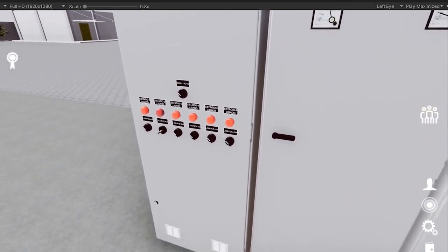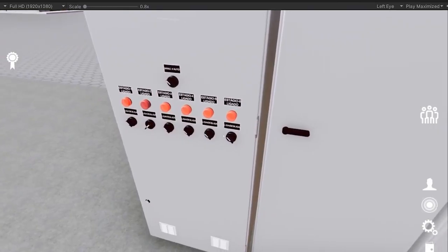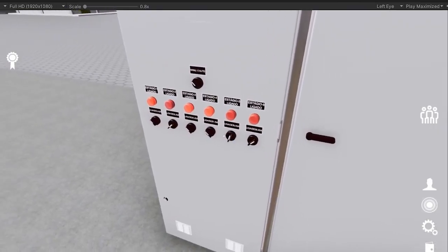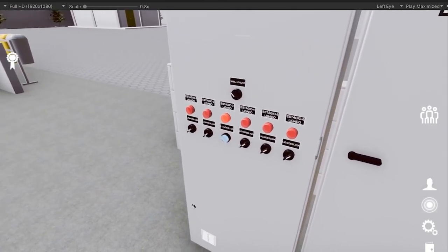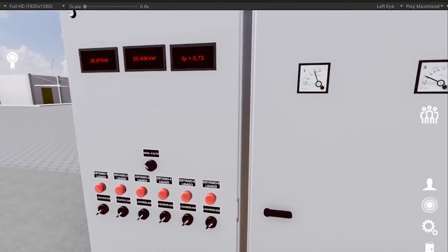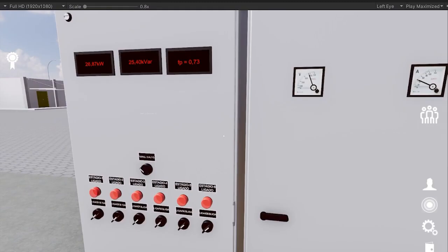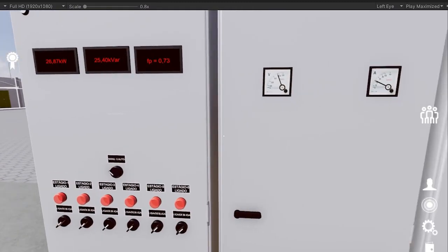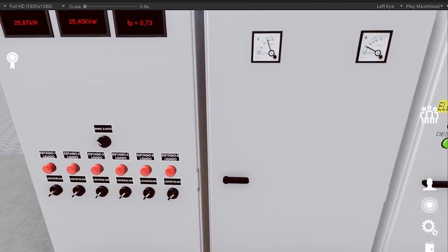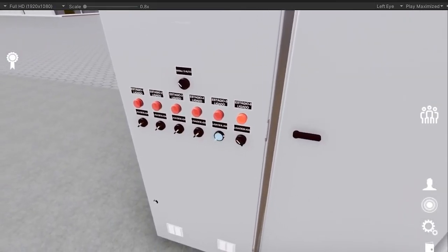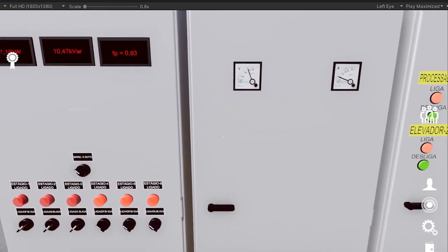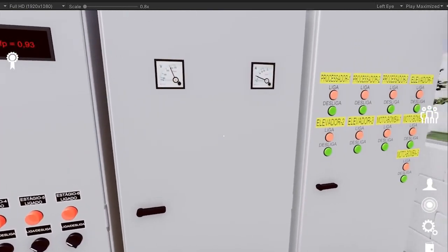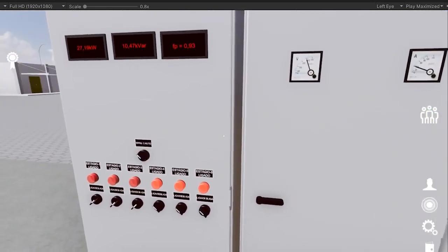This here, folks, I'm operating capacitor banks. I'm going to turn everything off. My power factor dropped to 0.73. And I have an increase in current. If I try to balance my power factor, my current drops. Anyway, folks, this is a matter of power flow.